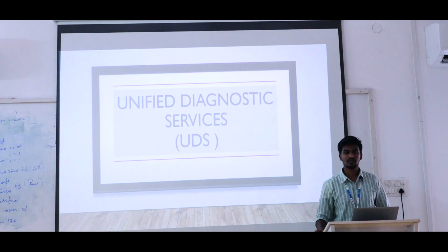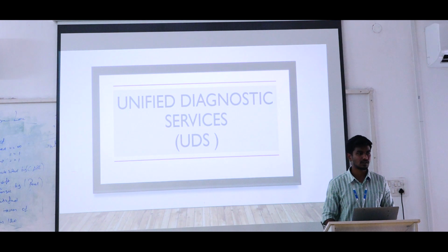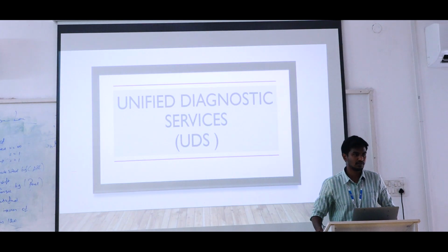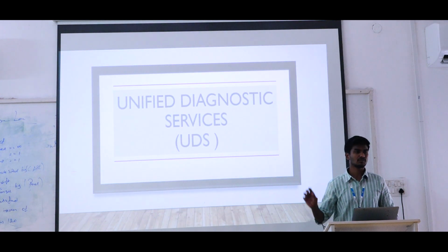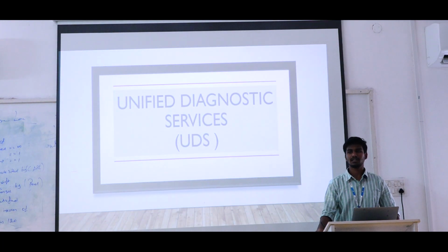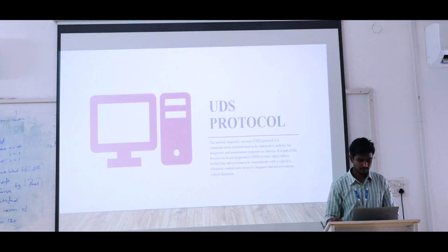Apart from that, we know about FlexRay and Ethernet. Same concept, it is also a communication protocol from client to server side. Here the client means our tester, which means the tool we are using for those services is called the client. The server is our ECU. Based on the client requirement, the server will respond. That communication is called diagnostics. The one and only protocol is Unified Diagnostic Services, which fully comes under error spotting and ECU flashing, reprogramming.